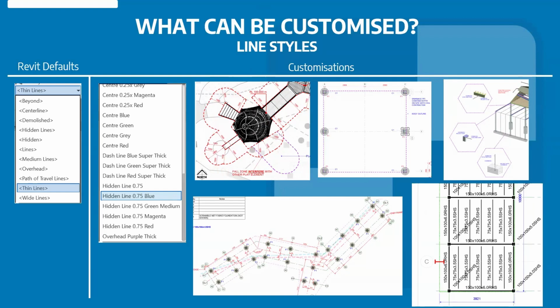Plus, sometimes we need to identify the floor outline or the roof outline when you're working on any structural project, then you can use your custom line style to represent them. Now you have the choice of drawing the line and then right-clicking and changing the element level, color and pattern or anything.